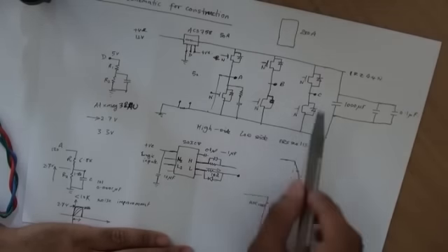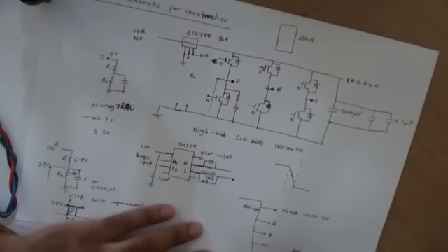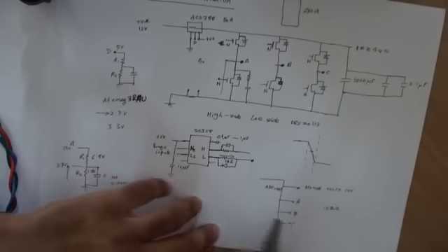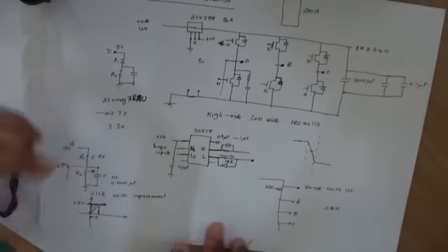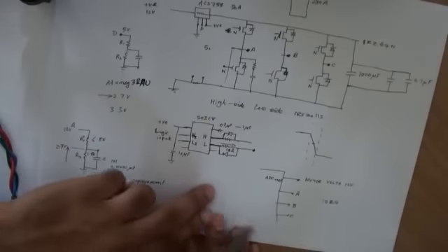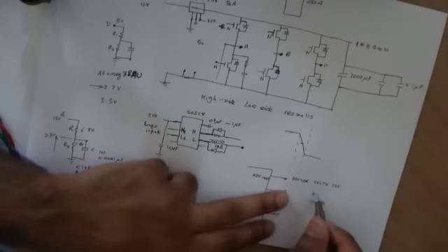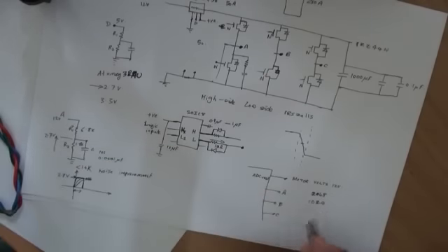To detect a halfway, you're really looking at a value of 1024 as your ADC raw value. With the Xmega 32 AU, the full scale raw value is 2048.